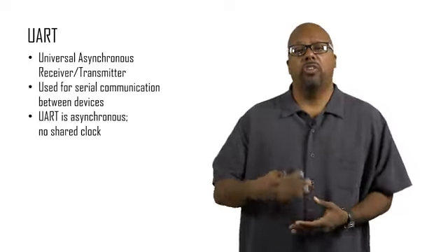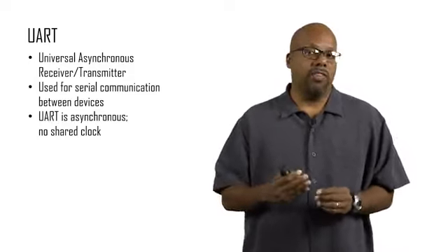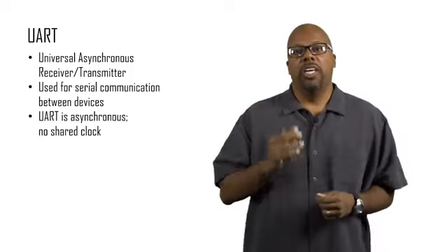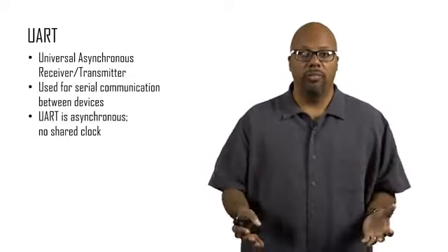And the system clock is going to run at a certain frequency. The rising edge has to travel from wherever the clock is generated to the chip, and there's a certain amount of distance. Maybe it's traveling this far, but these things are fast, so this far is a long distance. So it is important that the rising edge arrives at every destination at the same time, or very close to it. That's the assumption for all of our systems, that all the parts on your device that are receiving the clock all receive the rising edge at the same time.